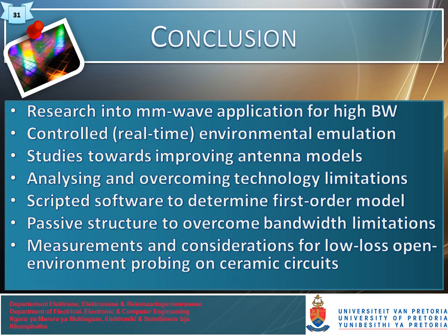Measurements from previous experience were optimized to also, through the use of passive components, eliminate the requirement for bond wires on high frequency connections, therefore eliminating the uncertainty and required characterization of the bonds, especially since machine bonding was not an option and hand bonded wires do have a large tolerance in profiles.